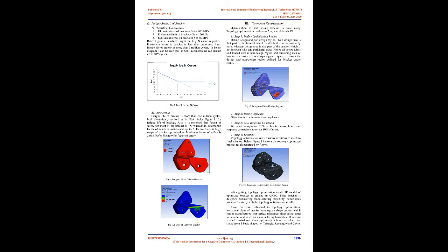Equivalent stress in original bracket is 67.9 MPa. Equivalent strain in original bracket is 536 microstrain. E. Fatigue analysis of bracket.